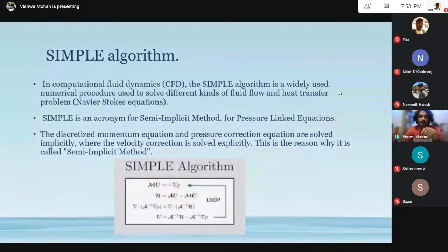Another one is the SIMPLE algorithm. It's used by Ansys. Basically, it's for pressure. When you solve the Navier-Stokes equations, the pressure is nowhere to be found. You can't explicitly find pressure anywhere. So it was developed to tackle that. You can read it over here.